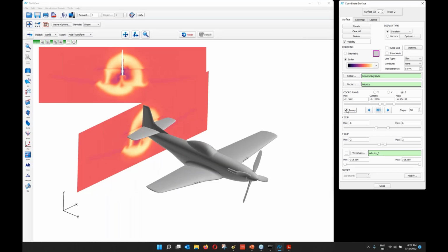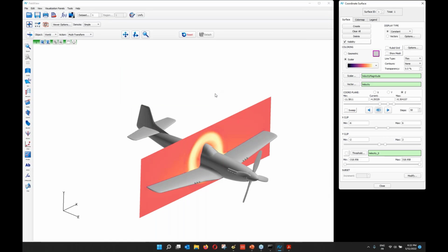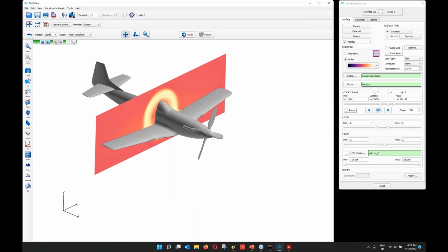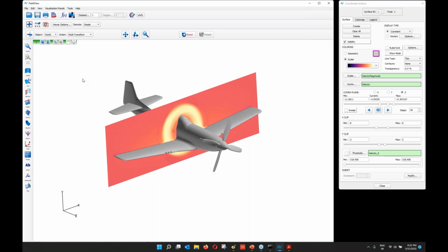Okay, let's get rid of the one I have on the side over here, and I'll show you another way to do something a bit similar, this time working with multiple windows. So FieldView has the ability to cut that graphic window, and as you do so, you can define what you're putting in that new window. So it's made with those buttons over here that show you the direction of the split. So we're going to split vertically. And I'll start with the instance.